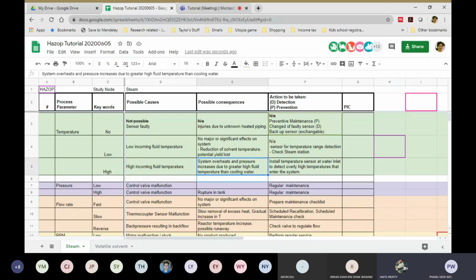The pipe itself will fail before we build up to that pressure, because when we talk about superheated, we also have to talk about the pressure that causes it to build up to that temperature. Go back to the ideal gas law, where PV equals nRT. Sometimes you may have forgotten some of the basic chemistry. When we have an increase of P, we can actually allow the temperature to go beyond 100 degrees Celsius.